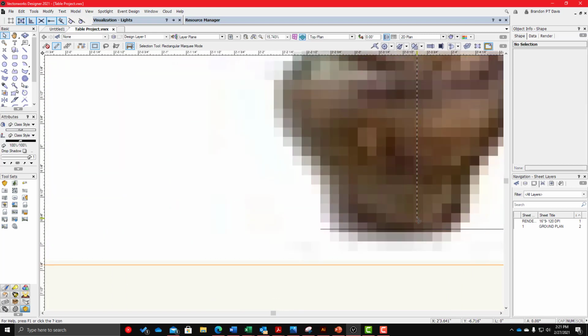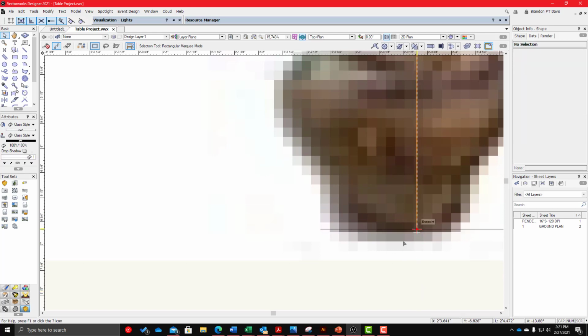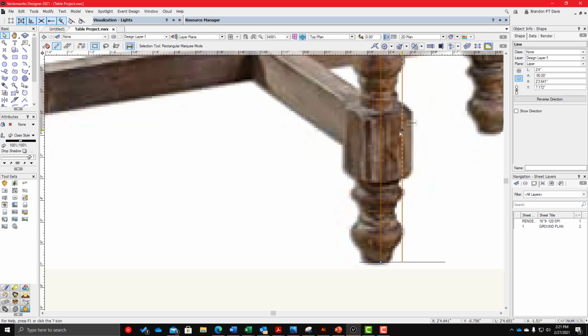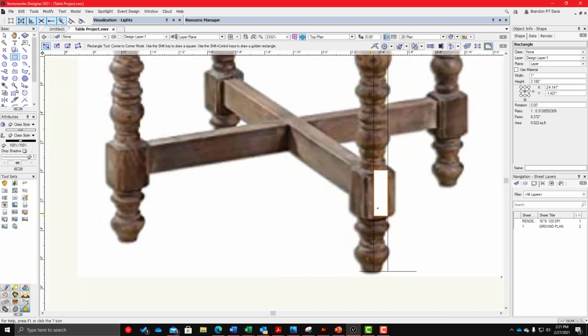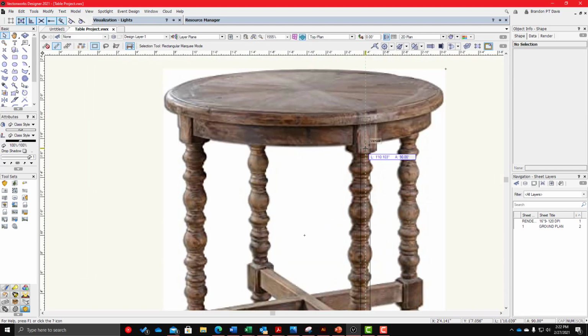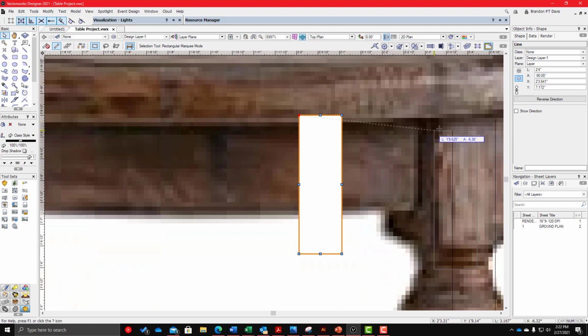And I want it to touch this bottom line, because this bottom line will be the reference for the model. Now I'm going to draw the rectangular parts, because these will be extruded later. This is about 3 inches. Then we have another one on the top. Since this one is going to touch our 2'4", our end point is going to be about here.